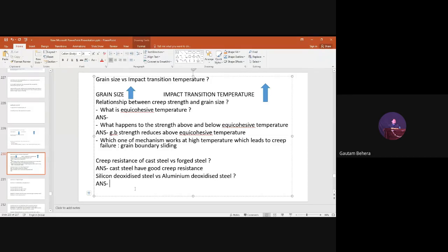But how is steel obtained? By oxidation. Very good. Oxidation of what? Impure iron. Oxidation of impurities. Very good. You can go through the UPE notes at least again, the chemical method of refining. You will oxidize the steel. So upon oxidizing the steel, what will happen? The impurities will get oxidized, but the iron will not. Impurities oxidizing means they will become oxides, and once they become oxide, they will move to the slag phase.